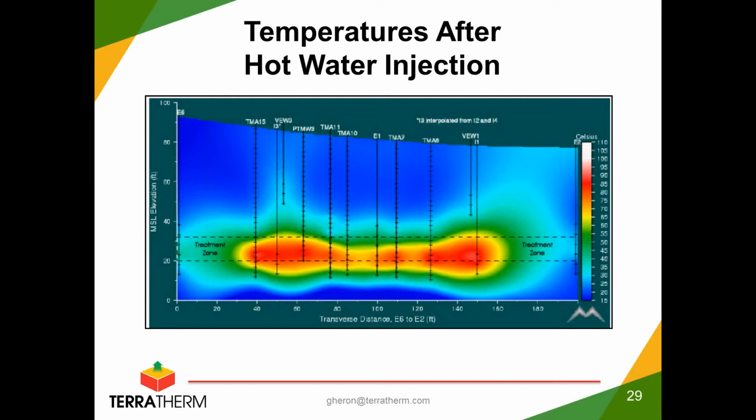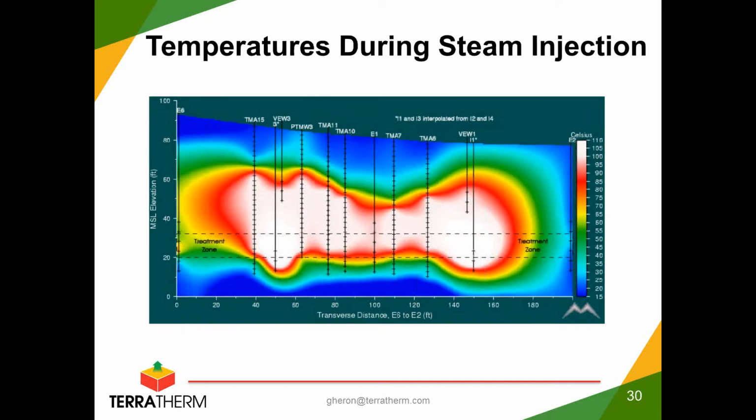If it had been effective, of course, it would be a much cheaper way to do the thermal remediation. We then turned the steam on and ran it for a while, and you can see in this picture how much hotter it got down in the treatment zone, designated by those two lines, but also that the steam wanted to rise a lot in this formation. Above the water table, these are sand dunes, wind-blown deposited sands with very high vertical permeability. So one of our tricks here was not to inject so aggressively that all the steam would just migrate up to the surface and be wasted energy.